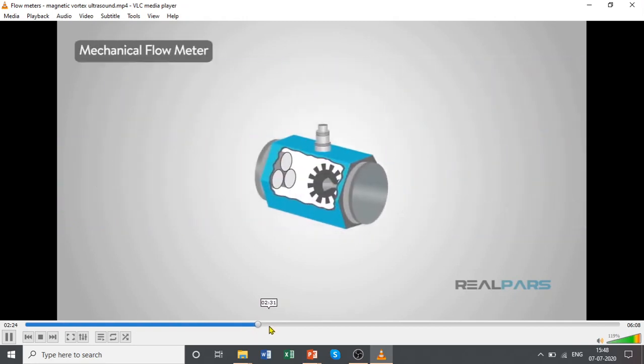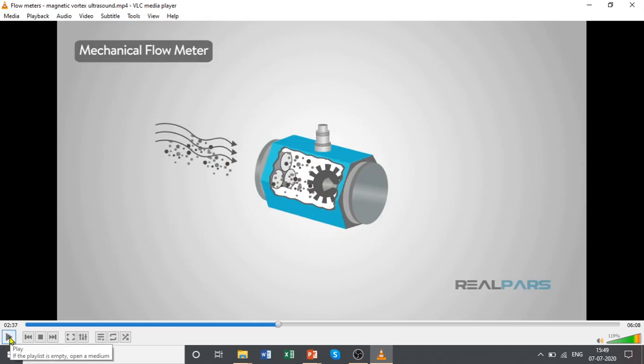Other flow meters work in different ways. For instance, a mechanical flow meter has some moving internal parts which may not fit with specific applications, such as dirty water that carries large particles that may cause damage or obstruct the internal parts. Like a turbine, right? So flow is there and the turbine is rotating. And therefore this kind of meter has a rotating part, and you don't want it to have solids. They can accumulate and foul, and because of moving parts it requires more maintenance as well.